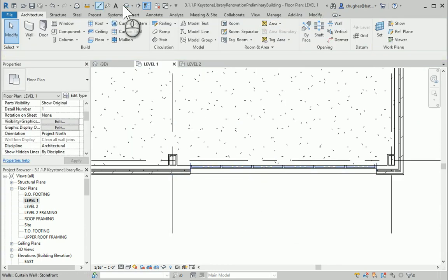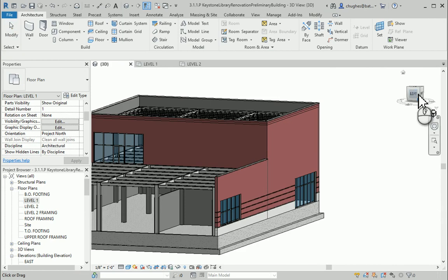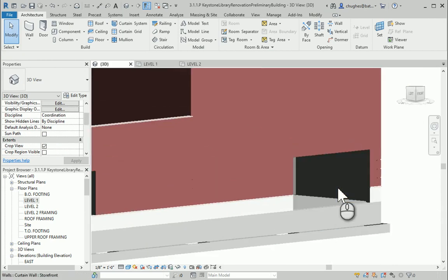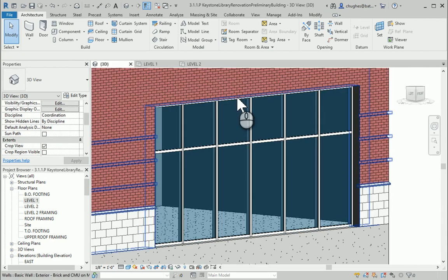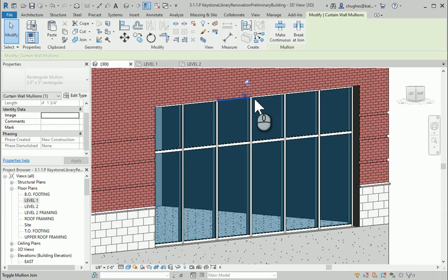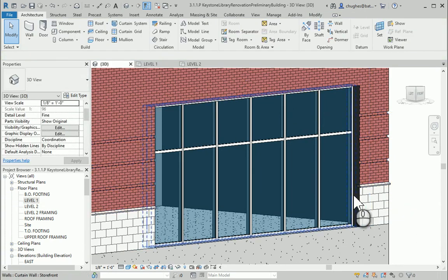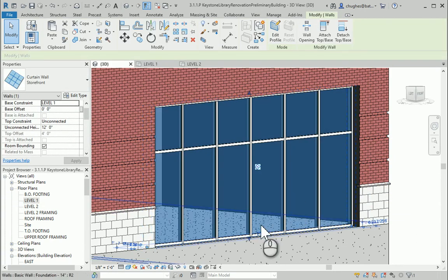Now, in the 3D view, I may want to take a look at editing some of the heights and everything. To keep this video a little bit short, I'm just going to show you with the height that they have set. This is 8 foot tall for the panes of glass. This is the default. So in this scenario, if I want to add a curtain door into this storefront, I can also do that as well.